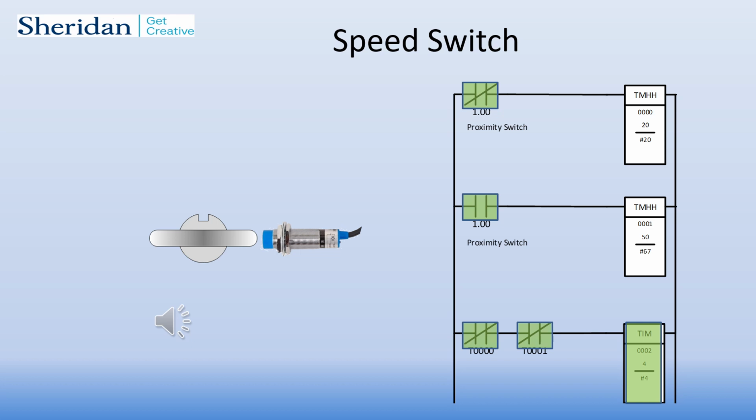And as long as those timers never become complete, the third line on the bottom with their completion flags will become true. And as long as it remains true for a prescribed period of time, it is said to have proved that the shaft is in fact turning. As soon as the shaft is stopped in one position or the other, one of the timers will time out, the proofing timer rung will become false, it will reset, and then we can take some sort of action, like shut a motor down or give an indication to an operator that something's wrong with the equipment, it has stopped.